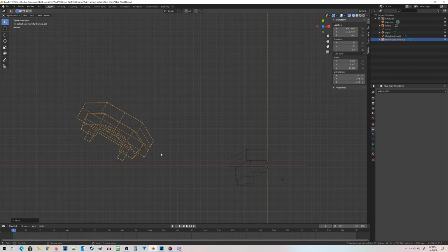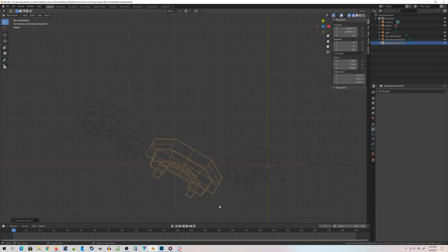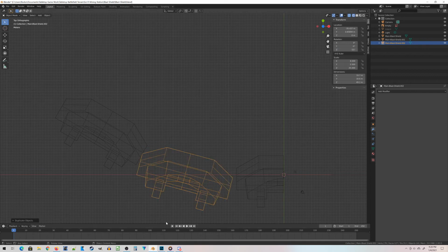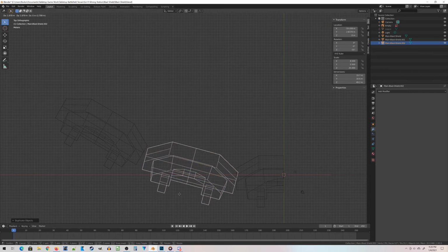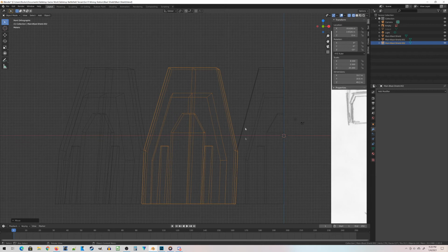Alright, that's cool there. Now I'm going to make the connector piece. So I'm going to actually take my copy here. Let's duplicate that, Shift D, and kind of approximately move it to where it should. We're going to set its rotation to minus 15, so it's kind of splitting the difference a little bit. And then I'm going to position it approximately about where I think it should be. Let me jump to the front view.